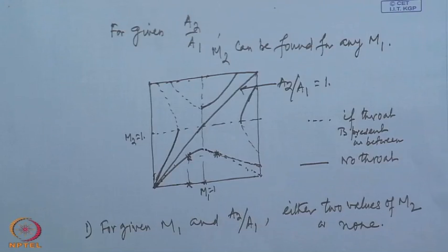For example, if the pressure and temperature at 1 are held constant, then a reduction in A 2 beyond its limiting value will result in a steady state with a different M 1 than what we had earlier, and a simultaneous reduction in the mass flow rate. However, this change in the inlet condition will be achieved after a transient period of unsteady